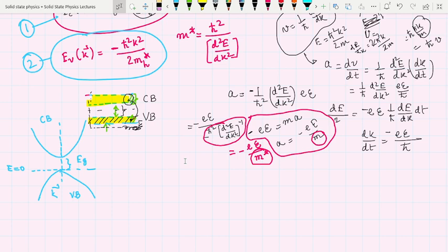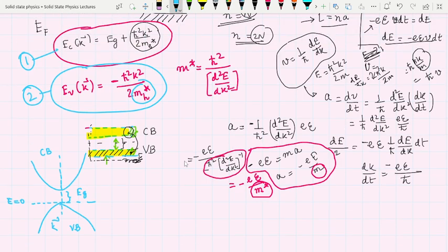Now the primary band structure parameters are thus the electron and hole masses. That solely depends on the energy, as you can see from the definition given by the mathematical formula. Now depending upon this structure we can classify the semiconductor as direct band gap and indirect band gap.